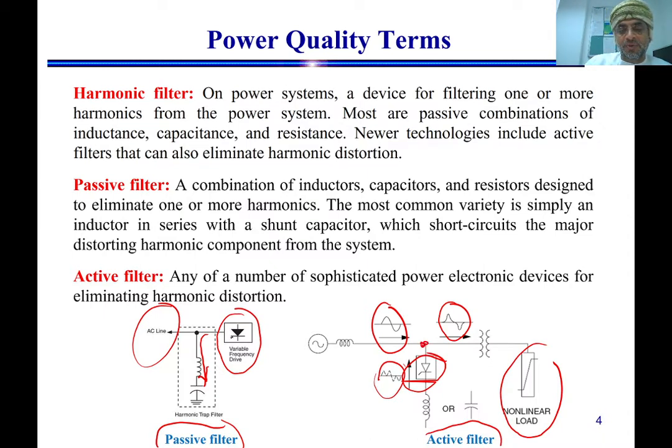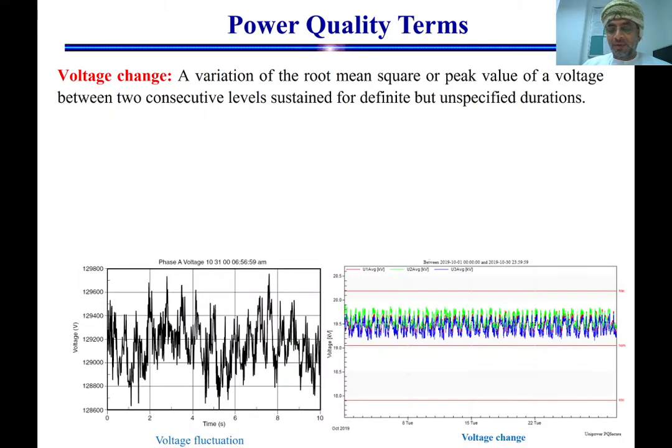you know, according to Kirchhoff's current law at this node, the summation of the current entering should be equal to the current leaving. So the current entering was supposed to be pure sinusoidal. Over here we have harmonic. Then over here also we have to provide a harmonic source such that this current will stay sinusoidal. Anyhow, we're going to talk about that one later on, inshallah.